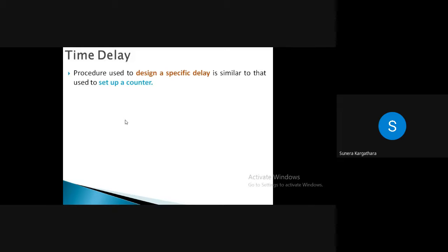Now as we discuss, suppose you are designing whether up counter or down counter and you are not putting sufficient delay in between two count, there is always problem that you will check for first count and you will directly jump to the last value, right? In between count value you are not able to observe due to insufficient timing, right? आपने जो time delay provide किया है in between two count value, that is not sufficient, so that's why you are not able to observe it.